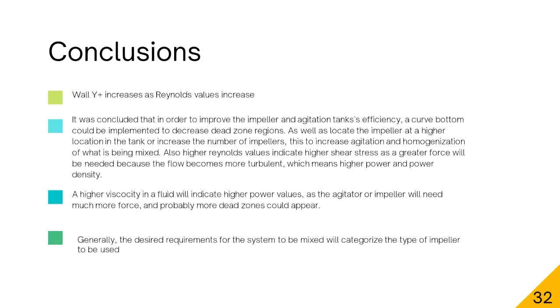Conclusions. While Y plus increases as Reynolds values increase in the impeller, it was concluded that in order to improve the impeller and agitation tank's efficiency, a curved bottom could be implemented to decrease dead zone regions, as well as locate the impeller at a higher location in the tank or increase the number of impellers. This is to increase agitation and homogenization of what is being mixed.